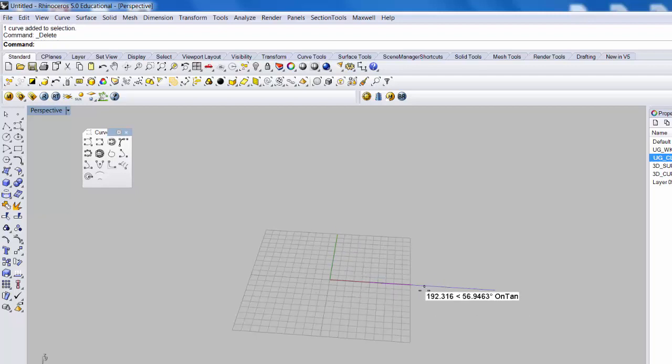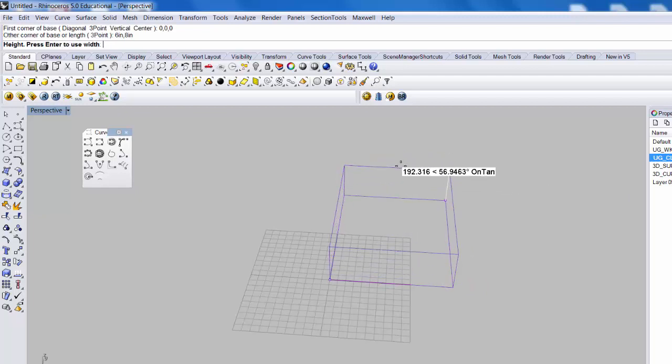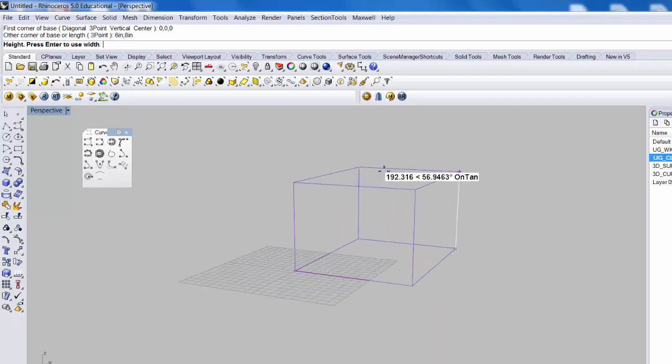So the way I'm going to do this is I'm just going to make my new file. Planar is on. So I set up my layers. So I'm going to start with the command box. And I'm going to type 0,0,0. And, well, I showed you that you could actually do 6 inches. That's in millimeters. So I'm going to do 6 inch, comma. Let's see if this works. I've never done that twice. Ah, that works. And then I have to hit the height for that.